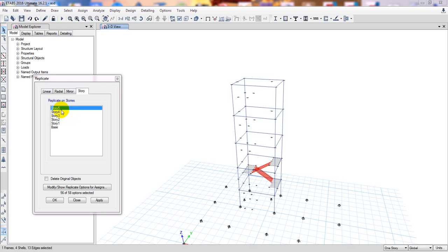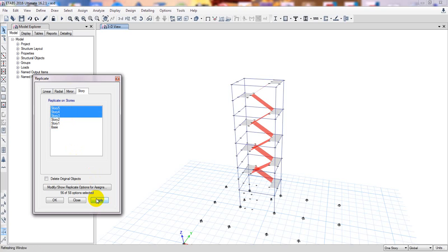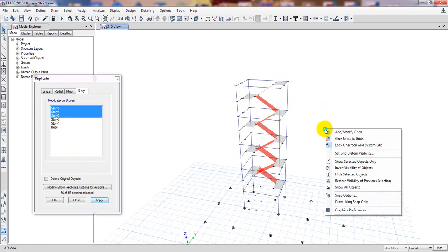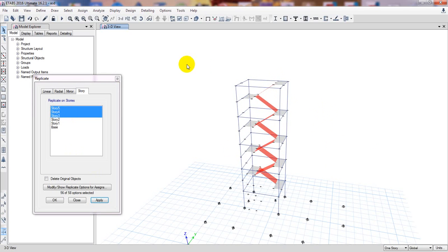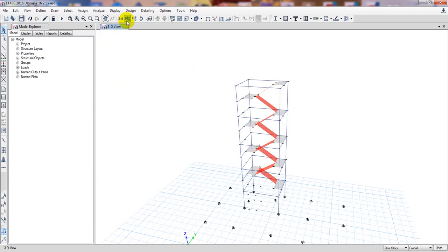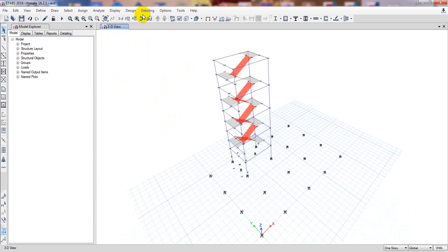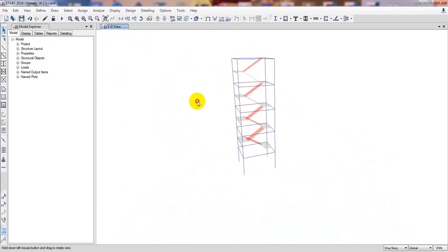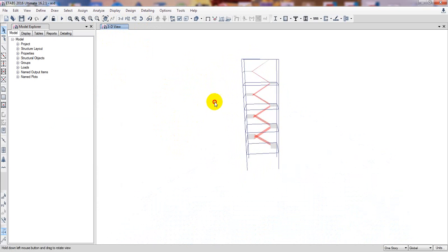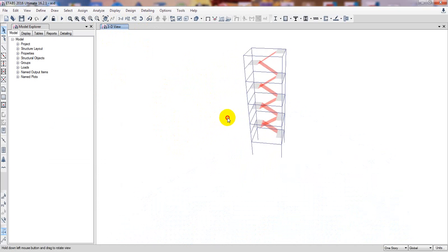As I've selected all data, now I'll select here 4 5 4 3, right, then simply click apply. Now see here, everywhere our all data is available. So here, here, here, and here. So we have successfully drawn our slab, I'll just close that, go 3D, and see here we have drawn our slab perfectly, right.